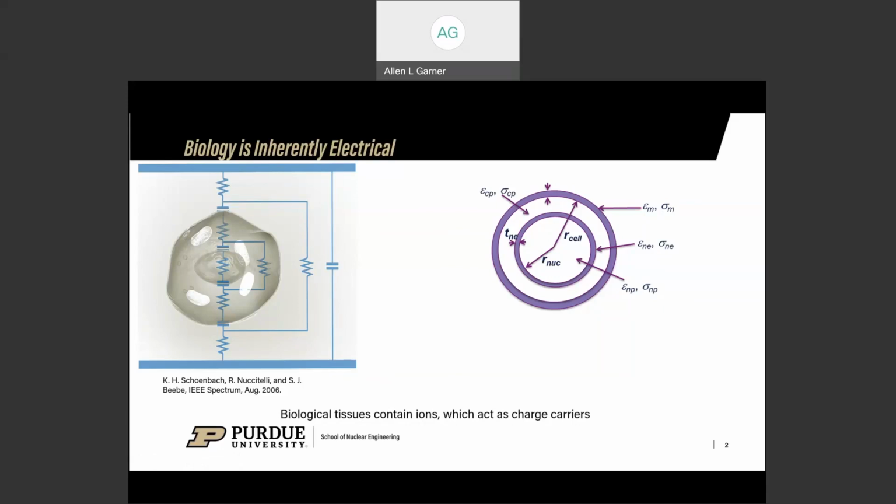So in many of the initial experiments, most notably a seminal work by Sale and Hamilton in the mid-1960s, they applied electric pulses to microorganisms, and they observed a rapid increase in the conductivity of the cells. A rapid increase in conductivity, from the electrical engineering perspective, is characteristic of what's called dielectric breakdown. You can create dielectric breakdown of, say, plastic materials in your high voltage devices. And what happens is you have a rapid increase in the conductivity of the plastic.